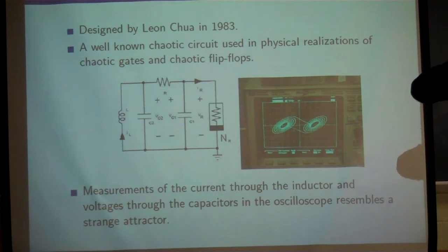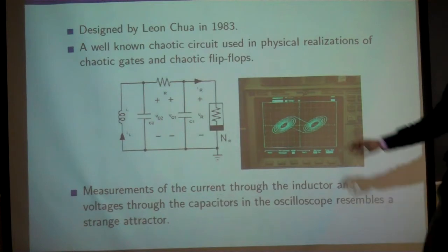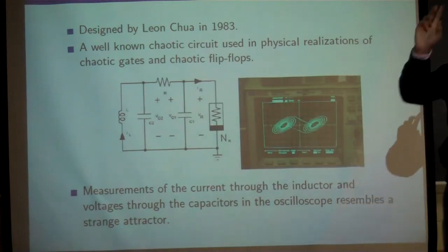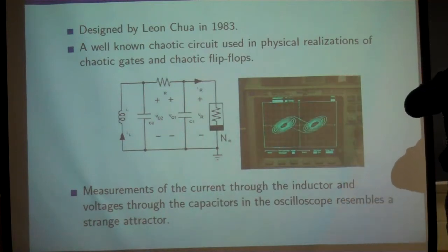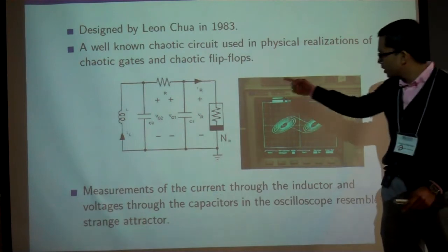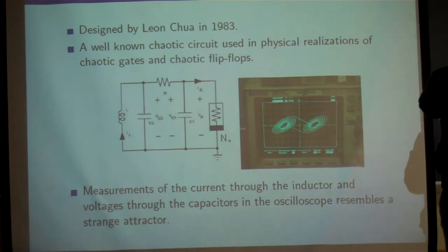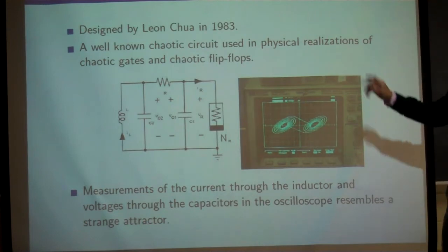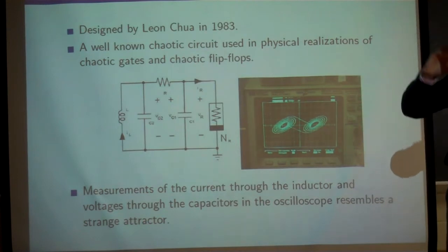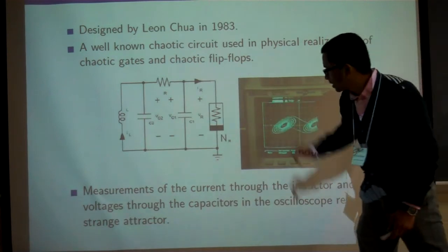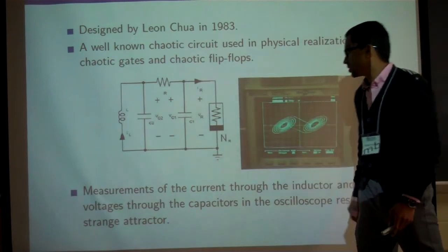I is going to be V over R. But in a nonlinear resistor, that relationship isn't linear anymore. So when Chua built his circuit with this nonlinear resistor, he had a resistor that acted as a piecewise linear function. So the current is a piecewise linear function of voltage. That's a way we can think of a nonlinear resistor.